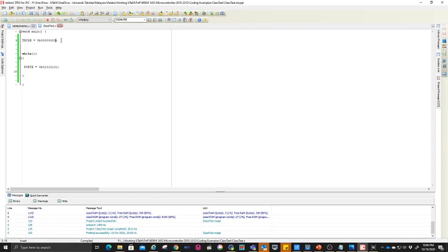This is correctly set up, and then here what you can do is put a delay underscore ms of 1000 milliseconds, and then you give another command, which is again PORTB equals 0B, then you invert all of this, so it's going to be 10 10 10 10, and then delay again underscore ms 1000, semicolon.